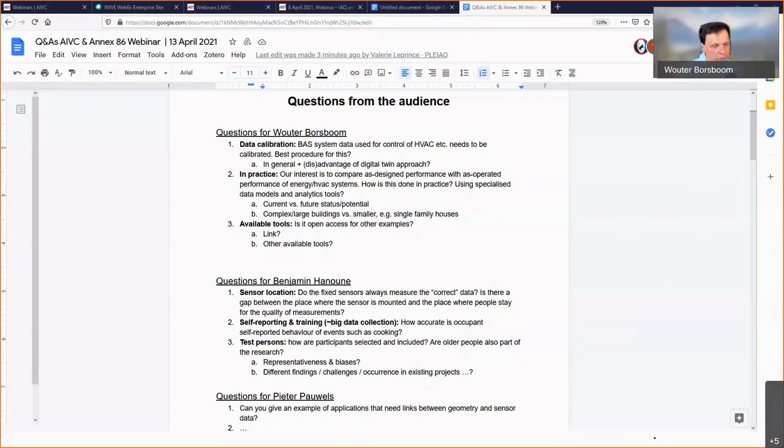We are also working for some projects where we will do model predictive control, and then the prediction horizon will be 6 hours up to 3 days. And we use this prediction to balance energy needs on a district level. But we also use these models to check if indoor air quality criteria are met in a housing project where we already collected data.